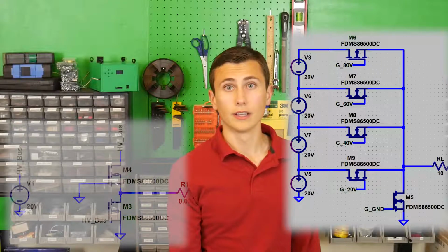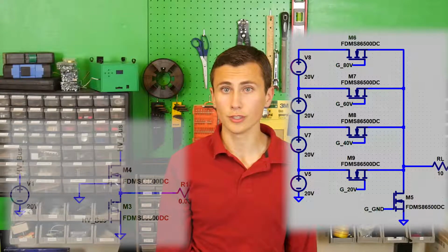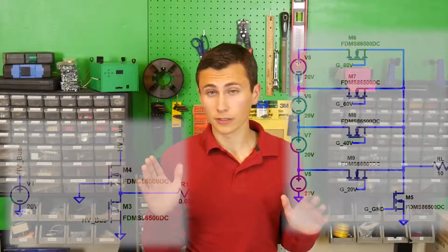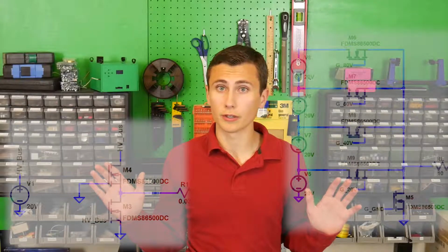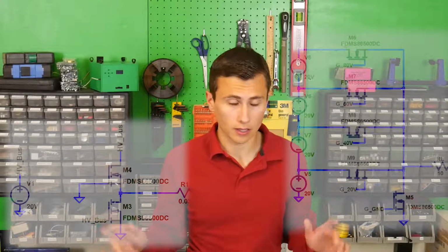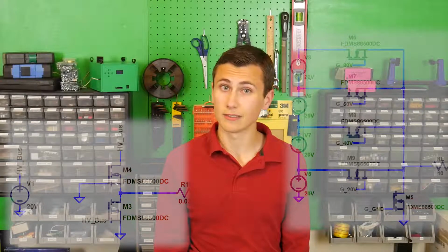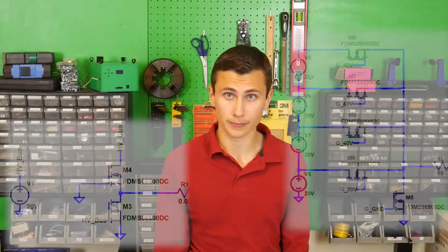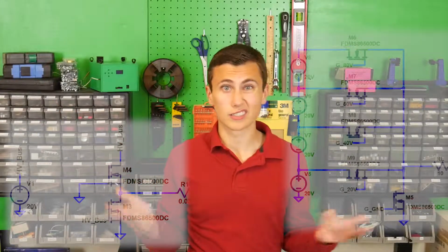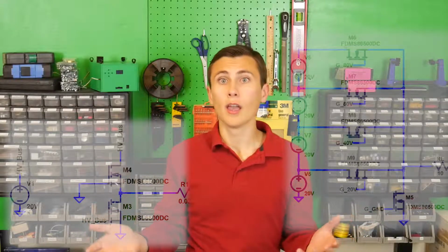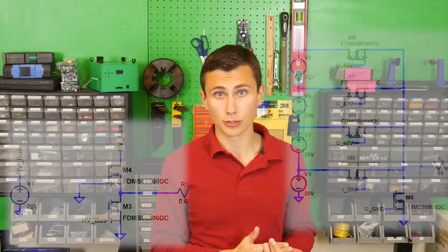Another benefit here, since we actuate our silicon switches in the same amount of time but have a smaller change in voltage: fair warning, the following sentence will contain words only familiar to persons tortured enough to experience differential calculus. The radiated emissions has the potential to be reduced since the dV/dt has decreased. For the layman, the radiated energy that could knock out your Wi-Fi, cell phone reception, and walkie-talkies may be decreased by switching less voltage on and off in the inverter output stage.